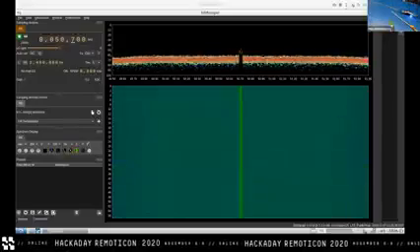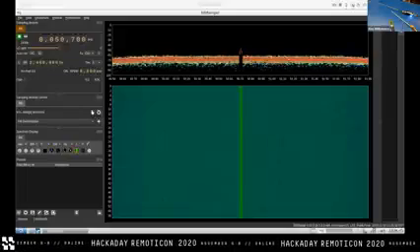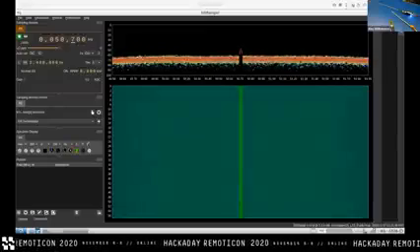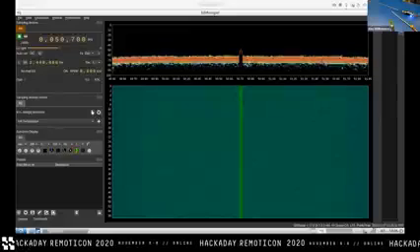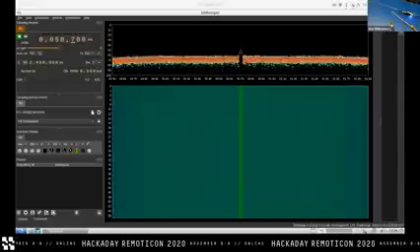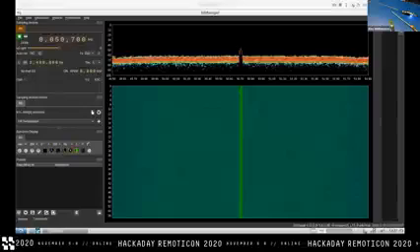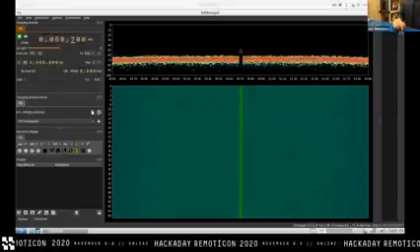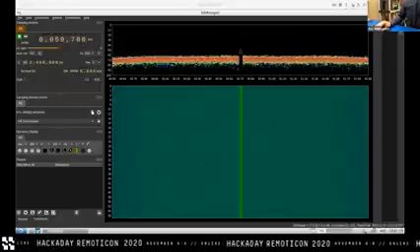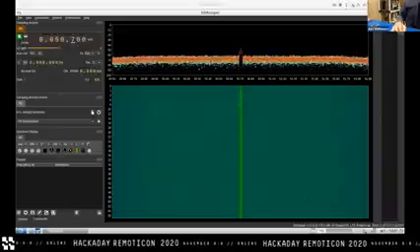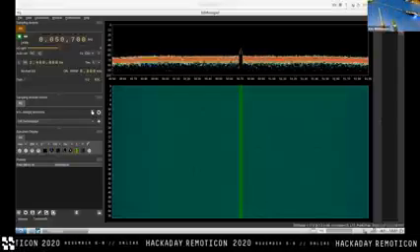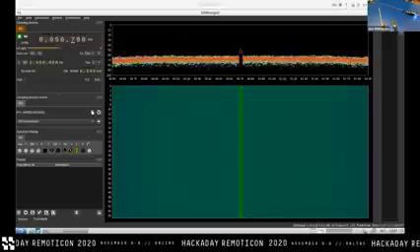And when you do, go back over to the code, top.v. And if you know Verilog, see if you can figure out and make sense of where that signal is coming from. And if you don't know Verilog, I guess basically just look for words that look like pins. And you'll probably be able to figure out where it's attached. And then go look at that trace with your loop probe, and you'll be able to see, oh yeah, it's definitely that particular pad that's getting lit up with high frequency and not this other pad or whatever.